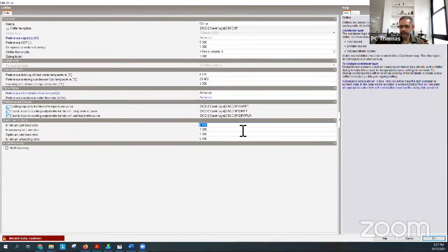At 10% of its capacity, it's working very inefficiently. And most practical engineers don't like to run their chillers that low. Using a control system, they will ensure that it doesn't unload to this value. The product suppliers will all tell you it works fantastic at 10%. I would say exercise some caution when you do that.